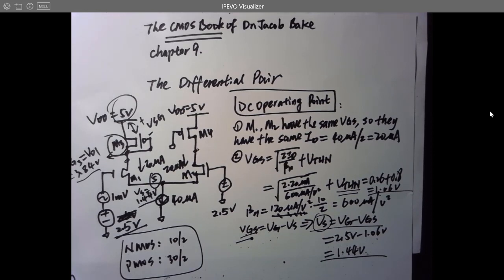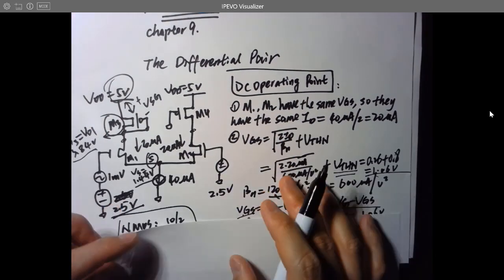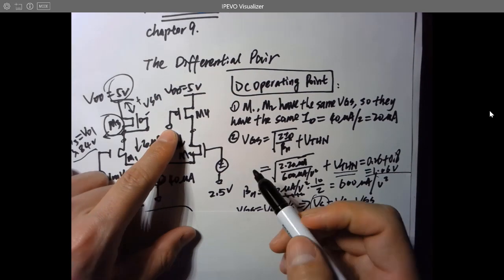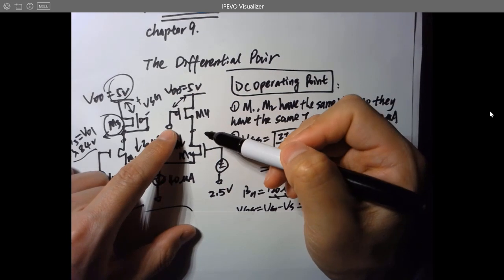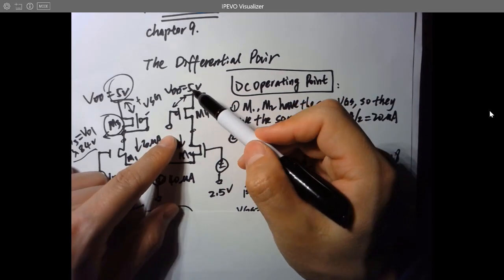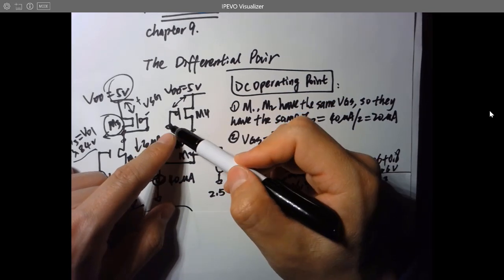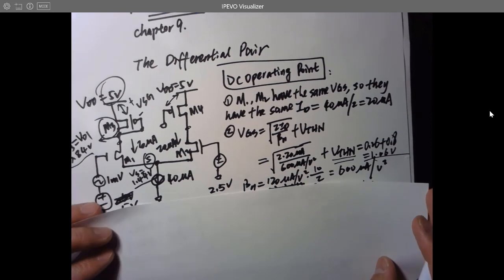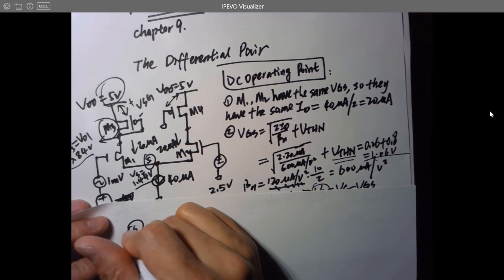Because we know that this transistor is pretty interesting because the gate is being shorted to the ground. So which means it's going to be a pretty large VSG drop. Okay, so the VSG will be 5 volts definitely, no doubt. Okay, so for M4, wait, right now we are at step 6.